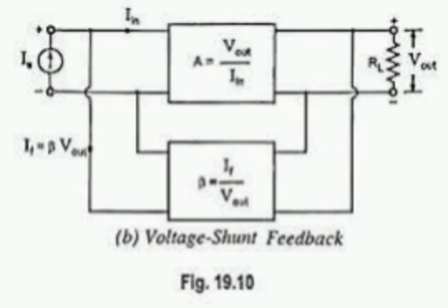For the inverting input, AC emitter current IE equals V2 by 2re. AC output voltage Vout equals minus IC RC, that is equal to minus V2 RC by 2re. Voltage gain for the inverting input, Vout by V2, equals RC by 2re. Differential voltage gain A equals RC by 2re. Input impedance Ri equals 2 beta re.